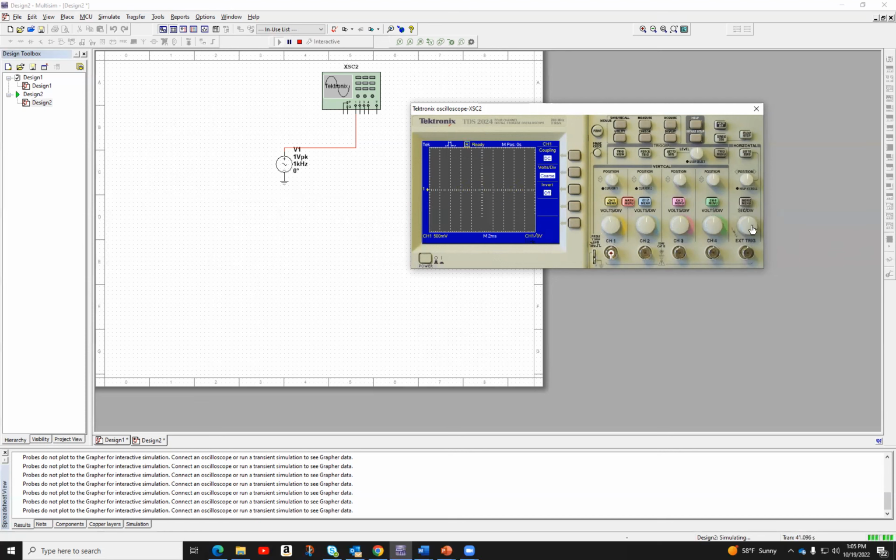The timing information controls all of the channels, okay? So I can control the individual volts per division with each of these knobs for each of the channels, but the timing information affects all of them at the same time. So again, if I move this knob either left or right, I'm changing the number of seconds per division on the x-axis, of course. And as you can see here, it's telling me that each of these divisions is now worth 500 microseconds. So if I keep going, one more, you can see a little bit of information.